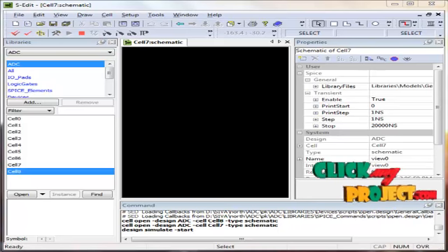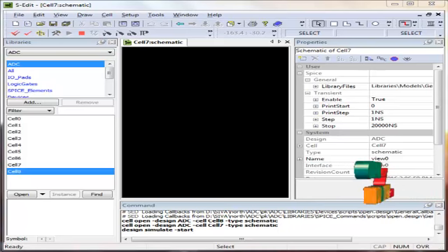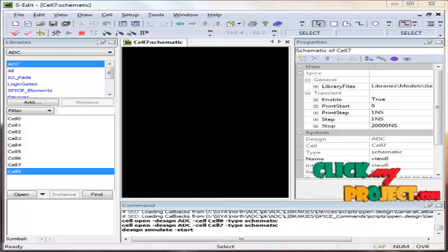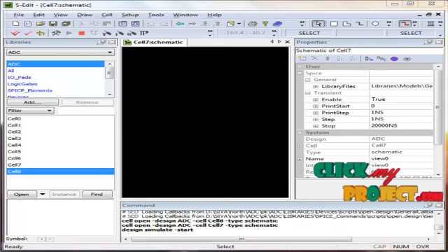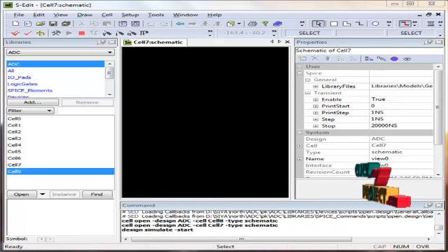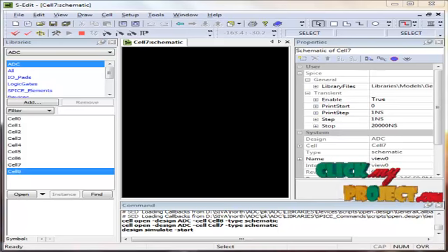The output is taken off a different node and an additional attenuation capacitor is used to separate the array into the LSB array and the MSB array. LSB B0 now corresponds to the leftmost switch and the MSB B5 corresponds to the rightmost switch.